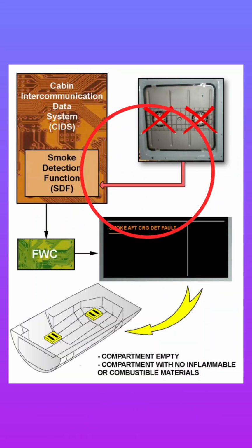Next one is your CAN bus, that is your controller area network bus architecture. It is primarily used for the aircraft's non-flight critical secondary systems, such as the cabin intercommunication data system and certain peripheral sensors, rather than the primary flight control. If you go into more detail, CAN bus is widely used to connect the cockpit hardware controls, such as switches, circuit breakers, and force feedback side sticks, to the main simulation computer.